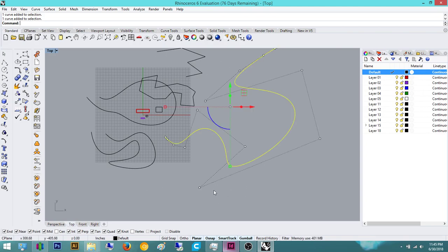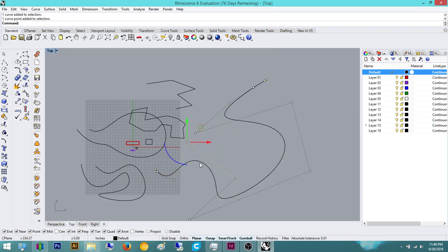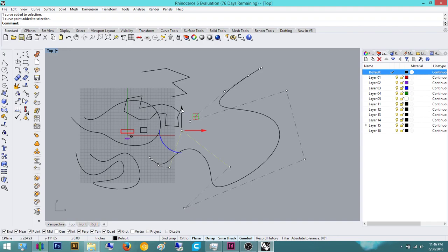So I would click on the curve I'd want to edit, and I'd see these points kind of randomly protruding out, as you can see. I want this a little more down. So what I can do is I can click this, and in the last tutorial we went over gumball, so we can actually use gumball to easily move it straight down, perpendicular, or parallel to the y-axis or the x-axis, as you can see from here. So we can literally click and just drag it down. And let's say I want this over here, you can see, just drag it.